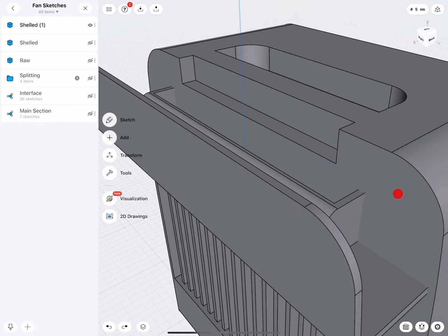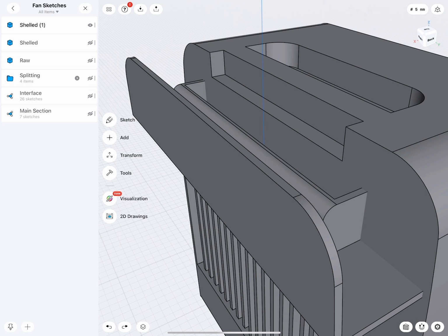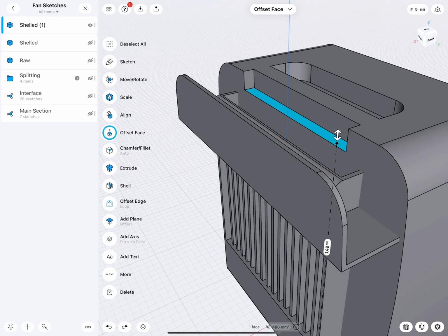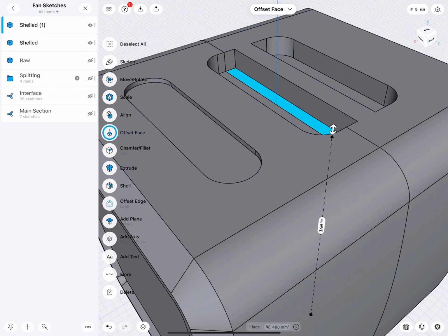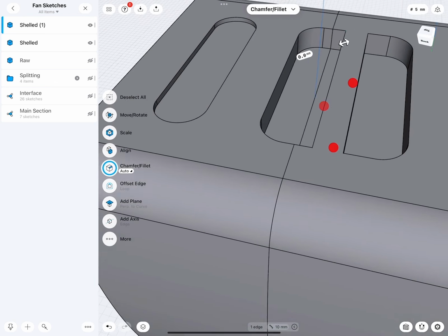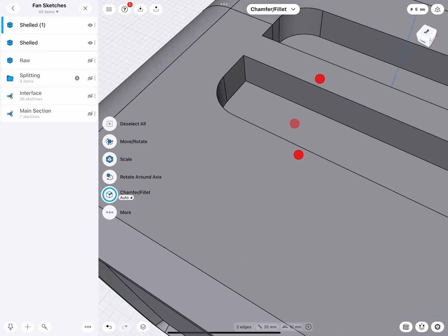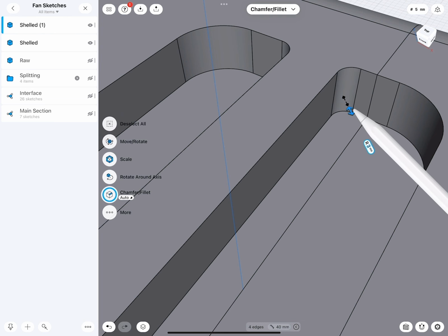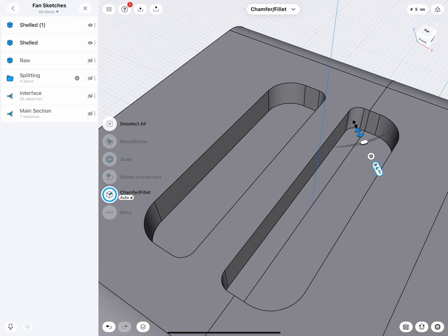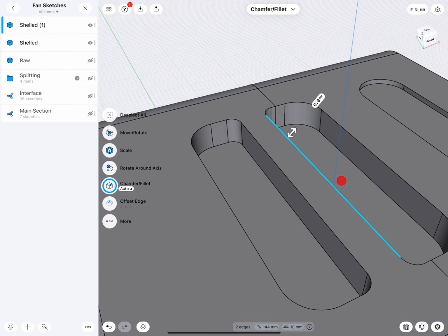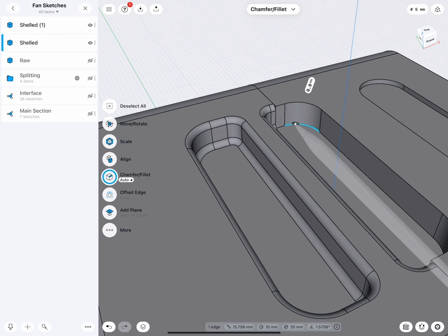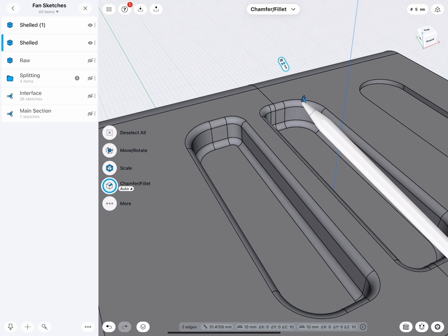Very good. That's kind of like a small three-dimensional measurement exercise, what I did, which means move 140. This is perfect. Then now we can show the other part. We can go back, select all those edges. 4 millimeters, this looks good. Then I will select all these edges and round them. 2 millimeters, this also looks good.